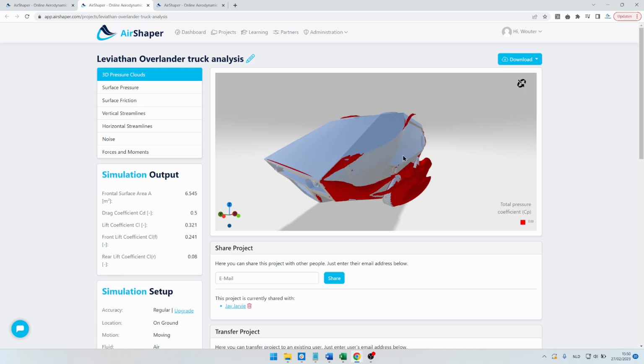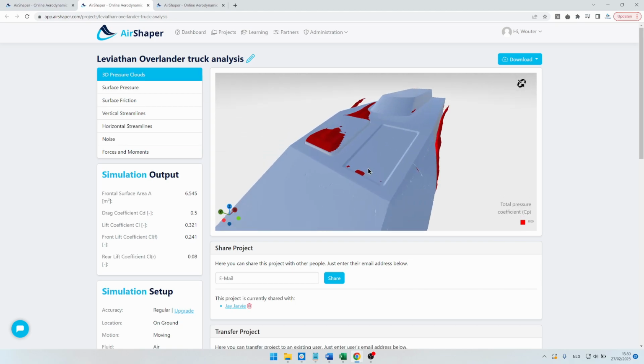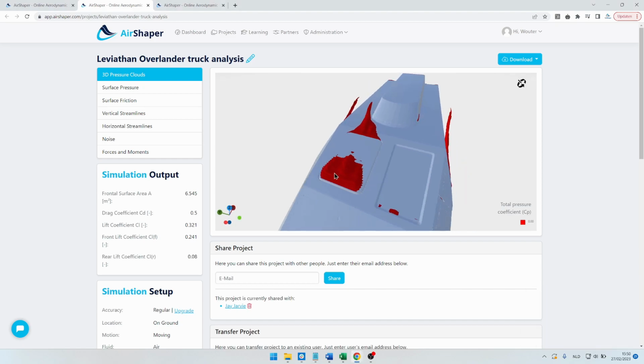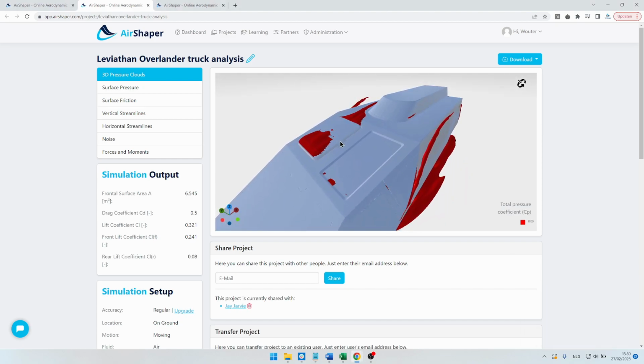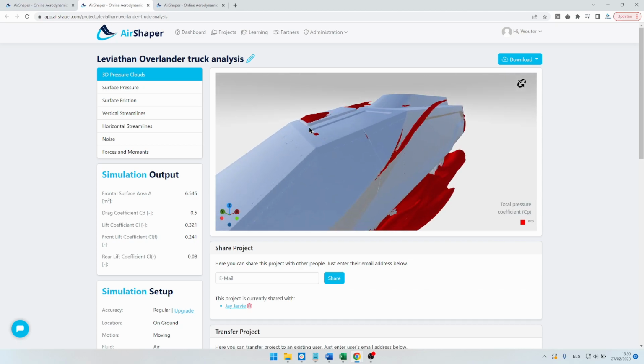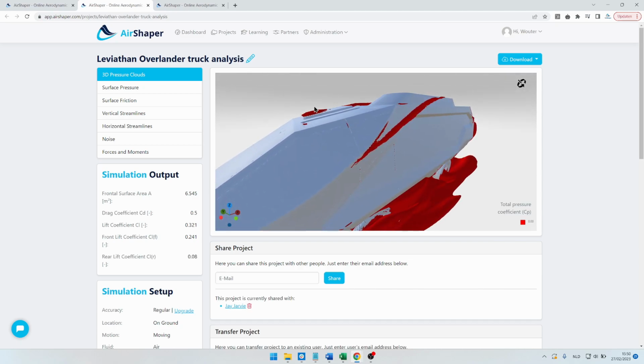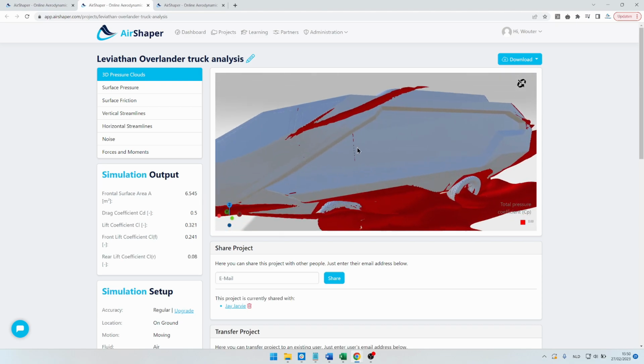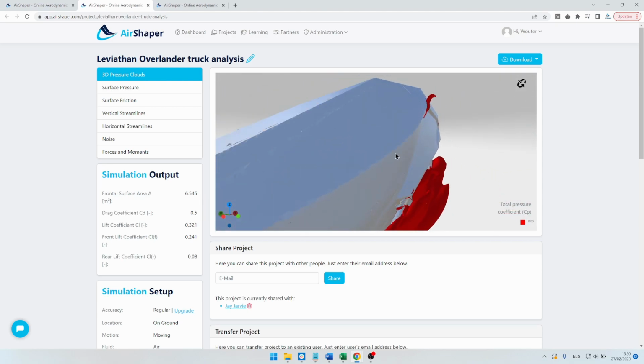So then if we continue downstream, we can see that there are surfaces like this one, for example, which is a hatch. It's very practical again, but if it's sticking out, especially when it has sharp edges, this generates flow separation. Another interesting area, again caused by a sharp edge, is this one here.